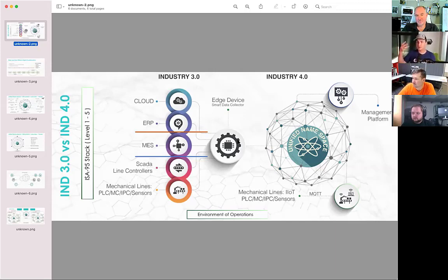A lot of people talk about OPC UA because it's so common. But OPC UA in the standard implementation fails on edge. It fails on edge driven, and it fails on report by exception. OPC UA is 9 times out of 10, no, probably 99 times out of 100, configured server-side pull response.